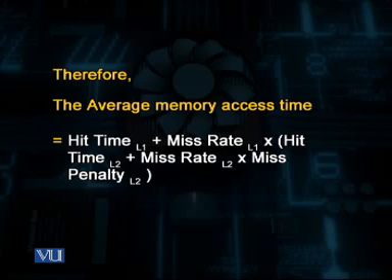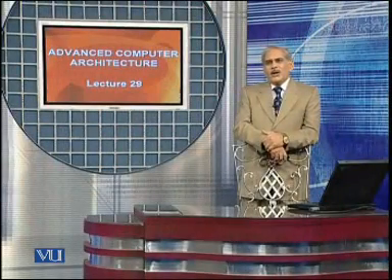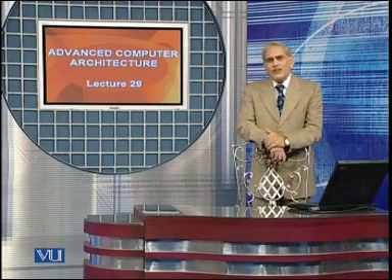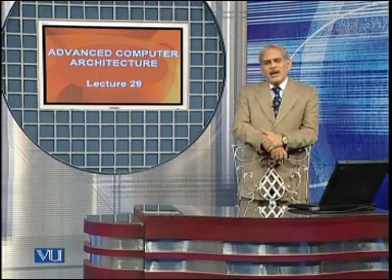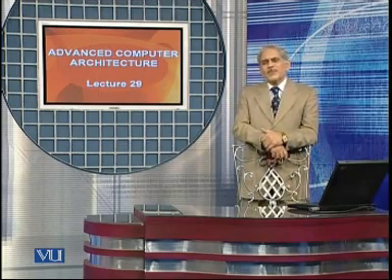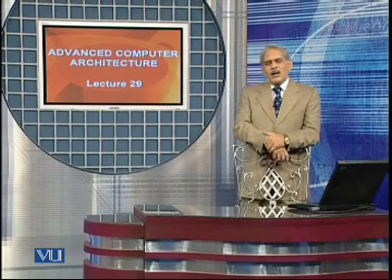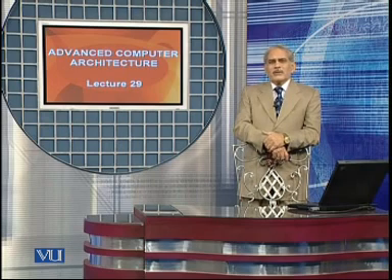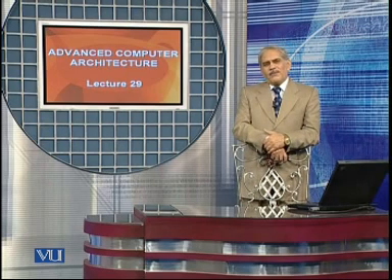And the average memory stalls per instruction for multi-level caches can be determined by expanding this expression for memory stalls per instruction, including the impact of the second level cache.